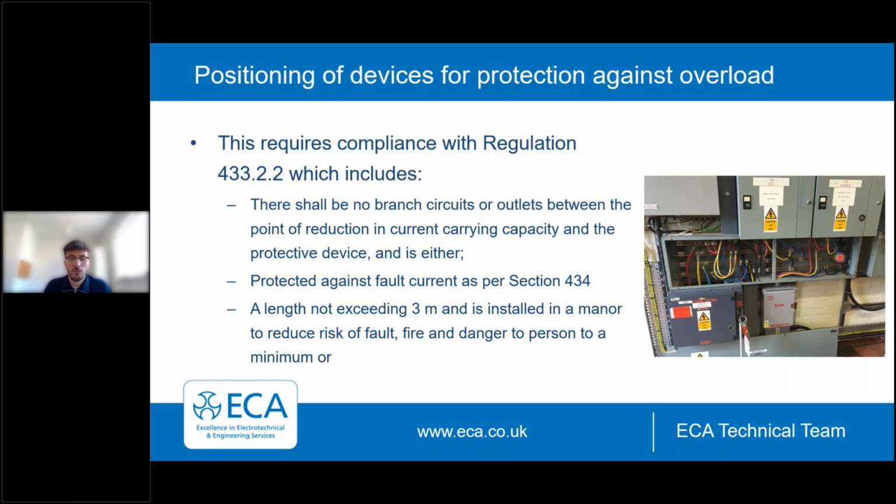With regards to the risk of fault, this may achieve it. It's a very short length of cable, or it could be seen that maybe this would be more suitable to have a double insulated cable coming down to this point, and that of course would then further reduce the risk of a fault condition between those points.